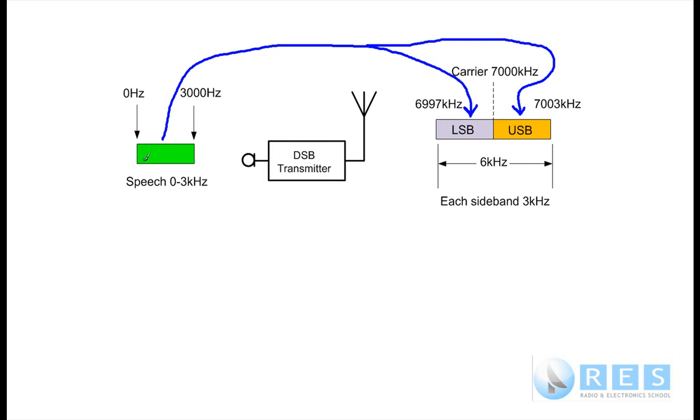So if we could see all the little undulations, all the voice frequency changes there, we would see them here as well. The only difference is that this is an exact map of the voice frequencies at radio frequencies. So all we've done really is a frequency conversion from 0 to 3 kilohertz to two pairs of radio frequencies.